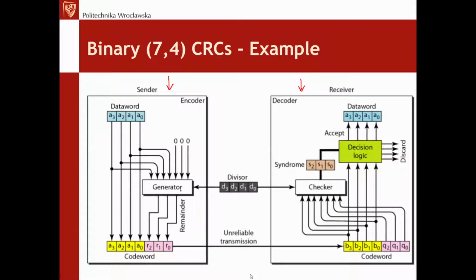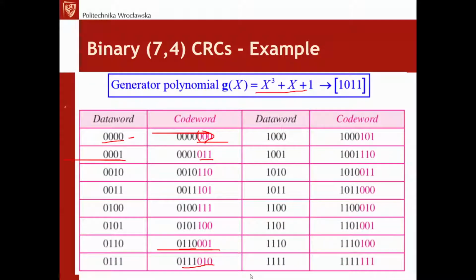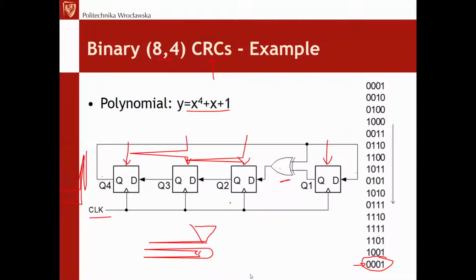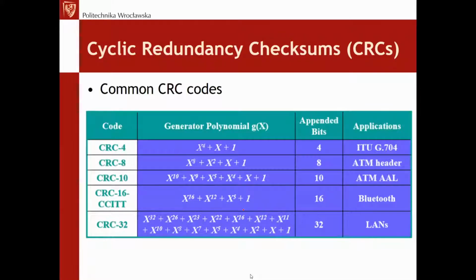Avoid doing it in a program way. If you don't have a microcontroller with a hardware CRC checker, then prepare a code word table. Avoid the algorithm. It's not very complex, and if you want, I can share a code for it, but from my perspective, it's very time consuming.